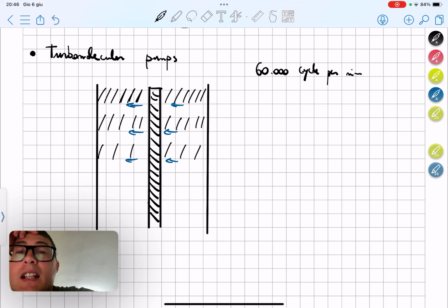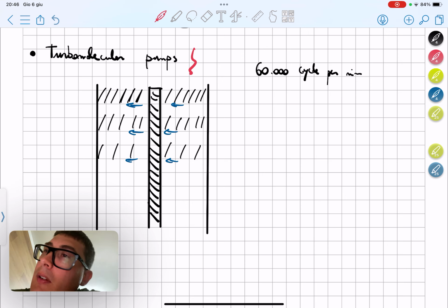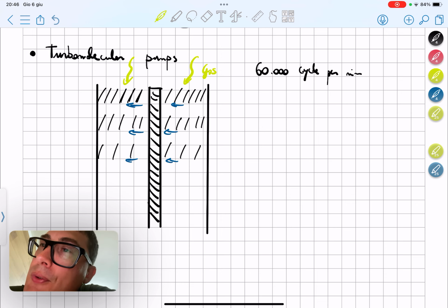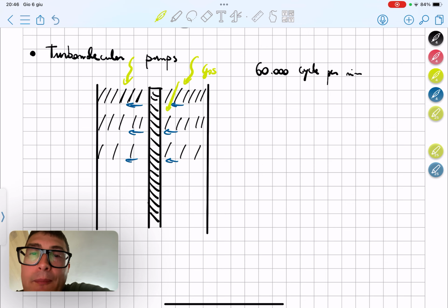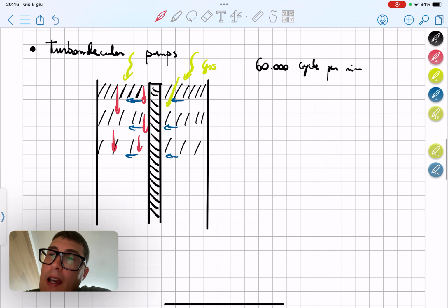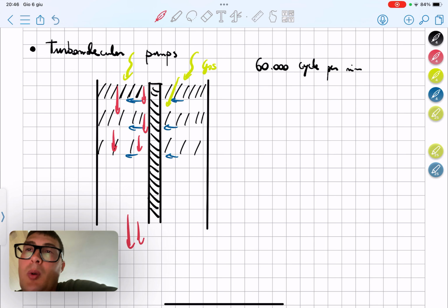And the physical principle of obtaining the pressure is by momentum transfer, because the gases that are coming, I think we use the yellow one, the gases that are coming from here will pass through the blades, okay, and we actually create a flux. Okay, we create a flux of gas that goes outside in the bottom part of the turbomolecular pump, and the